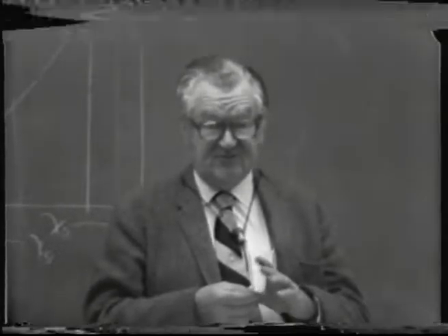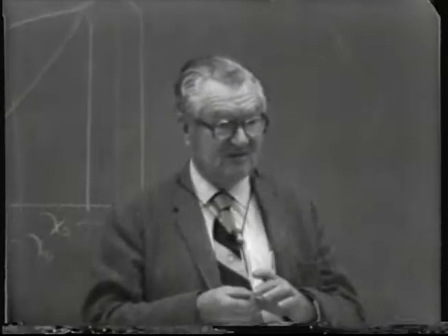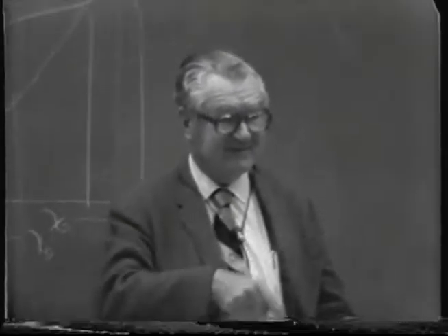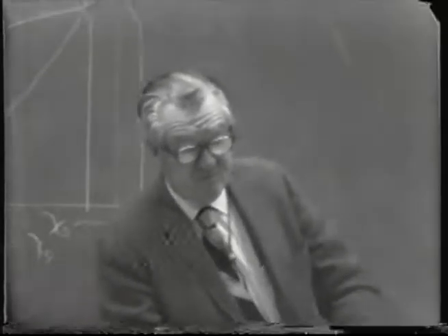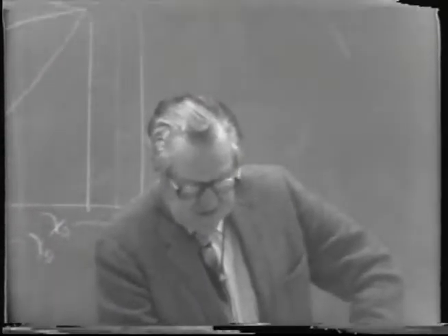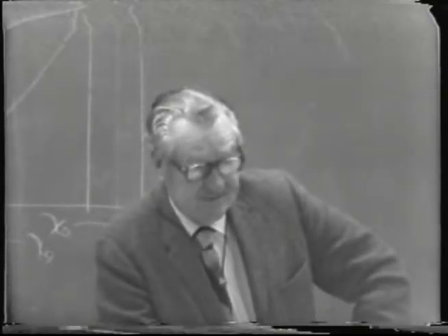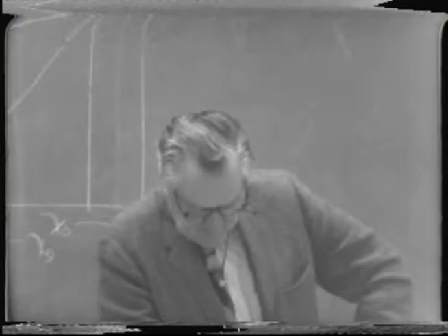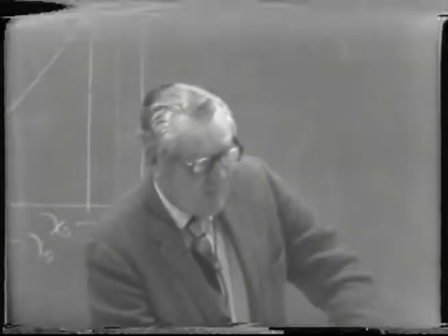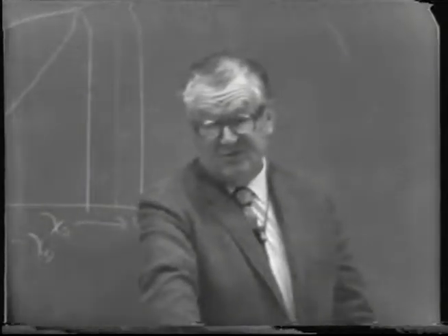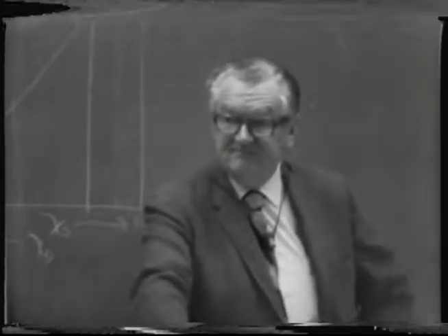And if you recall, 4 feet per second was the figure that we assumed in that illustrative problem that we went through last time for the stripping section, whereas we'd assumed 2 feet per second for the concentrating section. So I think these are in the ballpark, even though they're rather crude estimates of proper values.